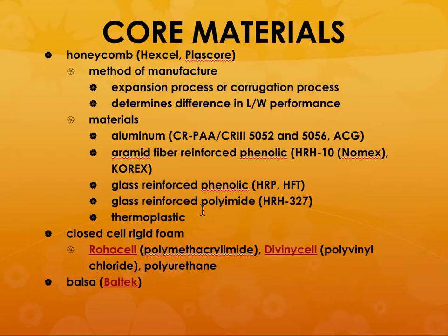You can also have foam type of materials, which could be closed cell rigid foam, called Rohacell or Divinycell, or polyurethane. Divinycell is a very lightweight polymeric foam. The other advantage of these foam type of materials is that they have fantastic acoustic protection against sound and noise.